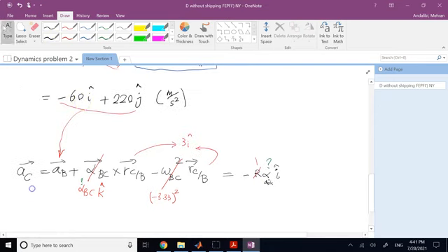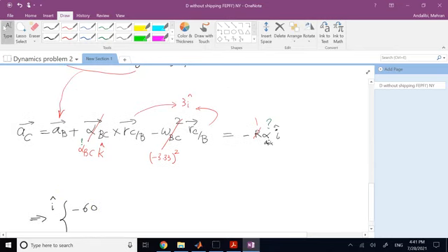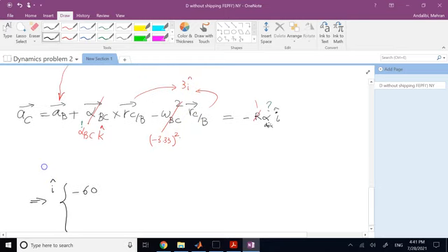If you look, i's, again, I have the I component for AB, which is negative 60. Here I have k cross I, which is j, so that's not going to do anything. Here I have this number times I, so that's a number you have to consider. And it's negative 3.33 squared times 3. Right? So this number is already 10 over 3, so it's 100 over 9 times 3 is 100 over 3. And it's going to be negative, so negative 33.33.